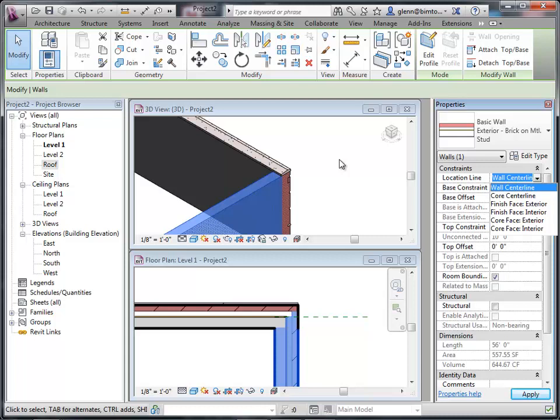You could say that you're measuring the outside face of the wall. On an existing building that you're trying to retrofit, often we'll measure to that because that's all we have to go with. But if you're designing new things, one of the most interesting places to measure to is really the face of the core.